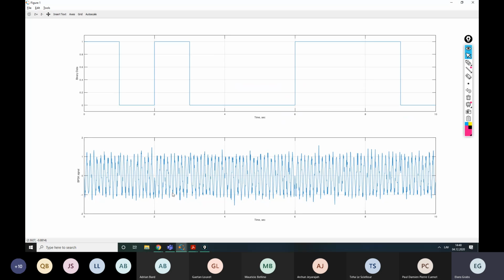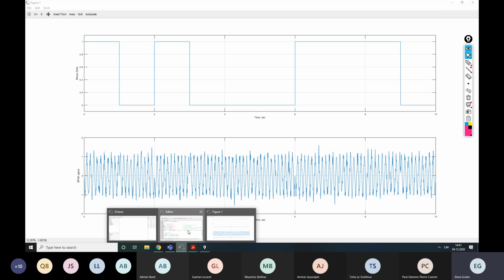Yes, so it adds much less noise than it should have, because there is an incorrect calculation for signal energy. Well, not incorrect, but it assumes that this is not a symbol, but rather a set of symbols. But this is not true, so we need to specify the energy in some way for this AWGN function.